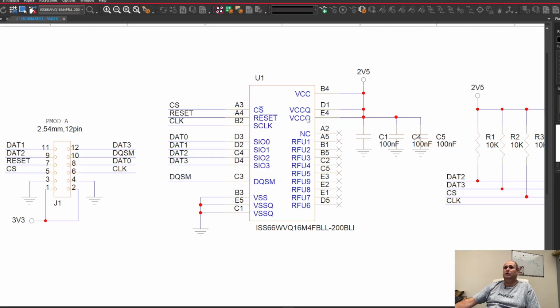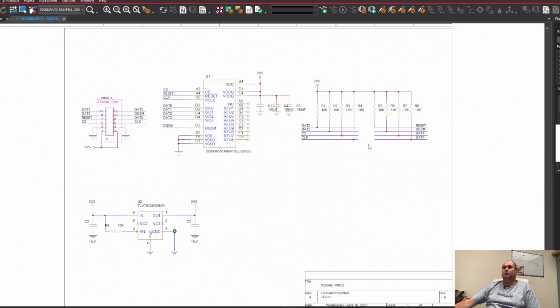They have this Q in the name, and they have this for the internal. So I put here 2.5 volt because I have a regulator in between which I'm going to bypass, but it's actually 3.3. Now it's a connector here and some pull-ups. So not much. Some pull-ups on the signal so they don't float in some stupid states. And of course this regulator which is going to disappear.